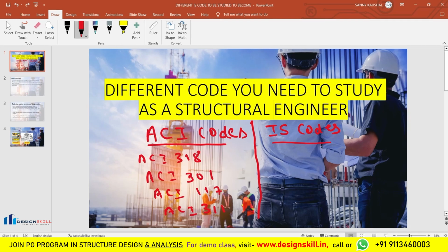Under the IS codes also we have more than 50 plus codes. But we do not need to study all the 50 plus codes. So what are the important codes that are used in structural design? We will study those codes only. So we have codes like IS 456, which will be used in structural design. Then we have IS 1893, which is an earthquake code that will also be used in structural design. Then we have IS 875, which is also one of the important codes used in structural design.